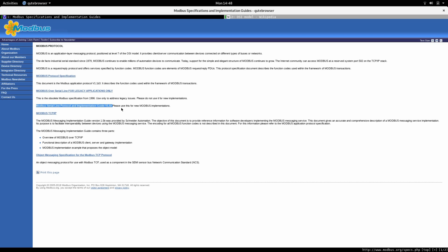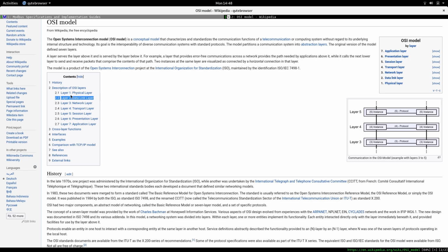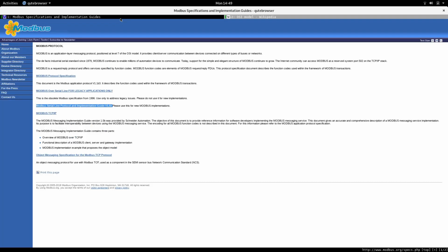So that document then just specifies the layer 2 data link layer type implementation, where it goes into both the addressing and the CRC is specified in there, which is the error checking on the frame. Is all done on that layer 2 protocol. But both those documents, the 2 combined, are probably less than 100 pages, so it's probably one of the smallest, shortest protocols you're ever going to read.